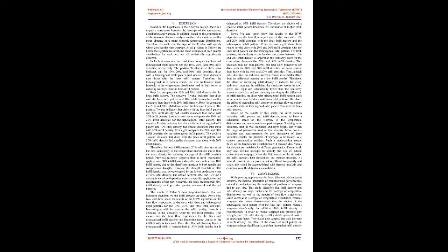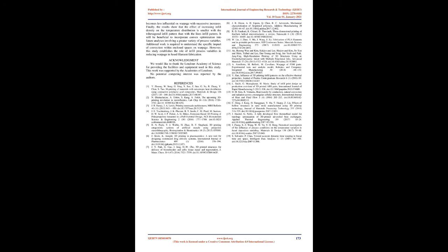This means that the heat flow trajectories for the lines and trihexagonal infill patterns are becoming more similar as the infill density is increased. Thus, the effect of choosing lines or trihexagonal infill is marginalized at 30% infill density but is enhanced at 10% infill density. Therefore, the choice of a specific infill pattern becomes less influential at higher infill densities.